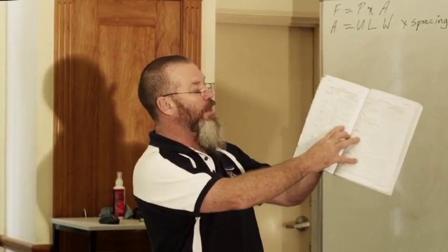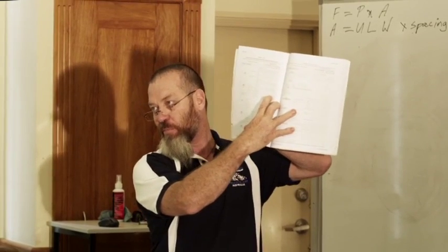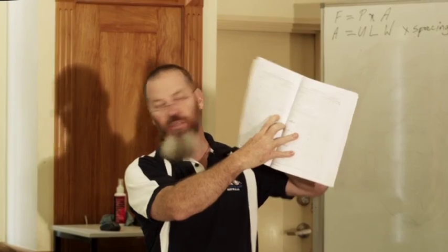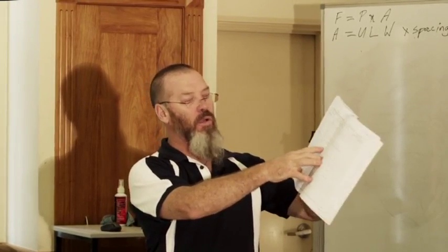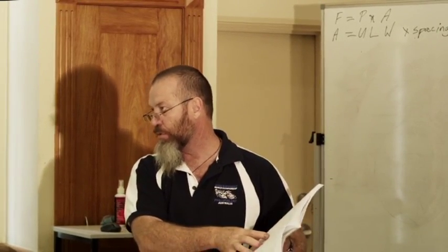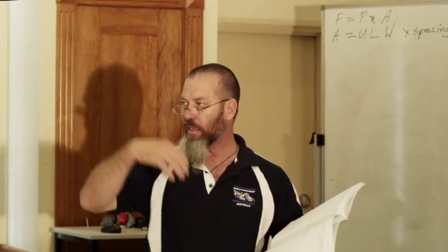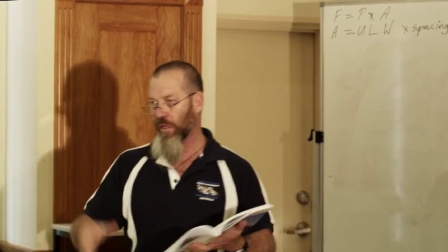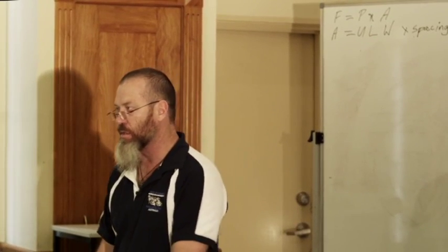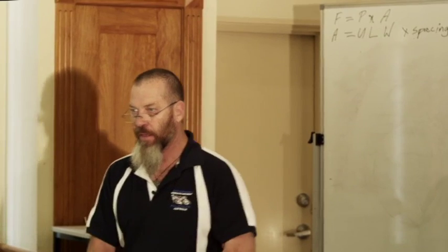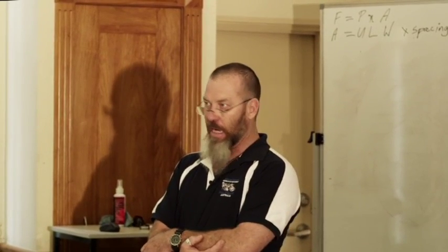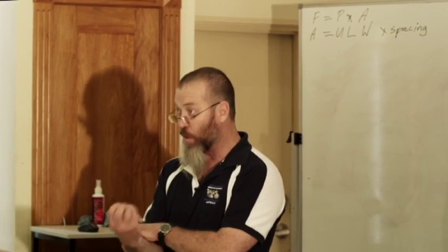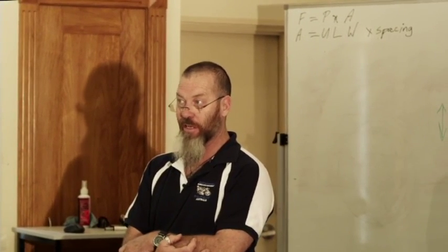So you've got to come down, and you'll see that 175 by 3.05 deformed shank nail is suitable for that 0.29 of a kilonewton resistance. So that's what it's all about. There's all these alternatives inside these tables. Now, let me tell you, that 0.29 of a kilonewton that I used as an example there is edge battens in N2 wind classification. That is what it actually calculates out at.